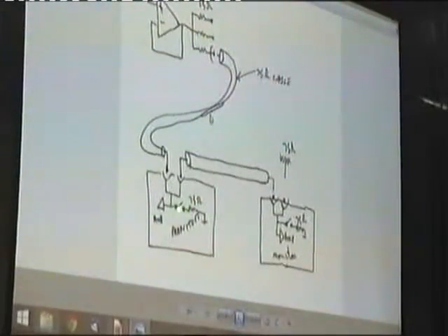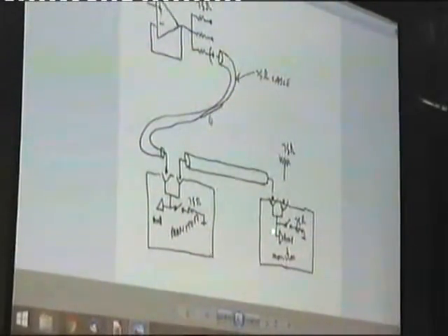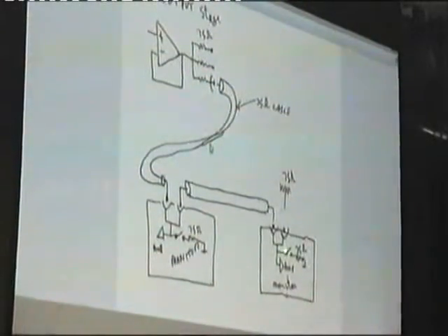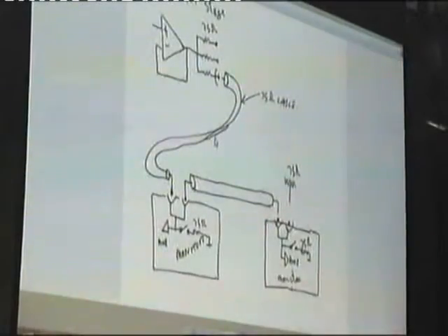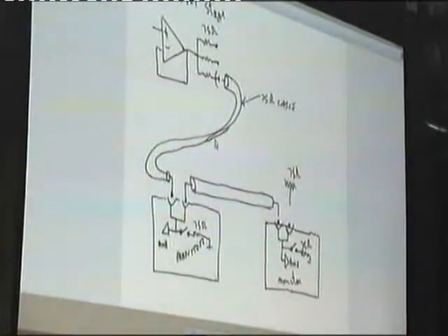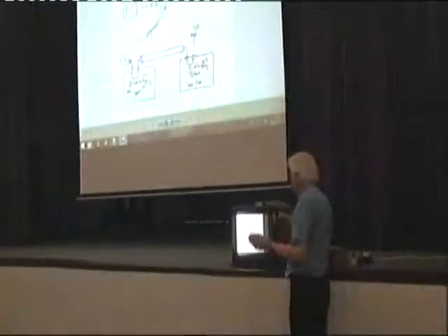So there will be 2 volts, 1 volt there when it's terminated, that's 1 volt peak to peak, 75 ohm cable through a monitor with the termination switched off and out to the next monitor, and there the termination is switched off, but it's terminated with an external 75 ohm resistor, and that works perfectly. What could go wrong? Well, what's going on here?